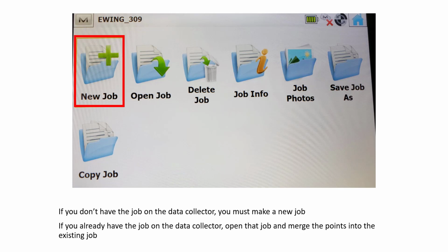So my point is, anytime you go out into the field and you make any type of changes to that survey file, whether it be adding a point, maybe adjusting some elevations if you're out there, or adding additional survey point data, make it a habit of coming back into the office and taking that data and re-uploading it into Civil 3D so you have the most current data you're working from that data collector.